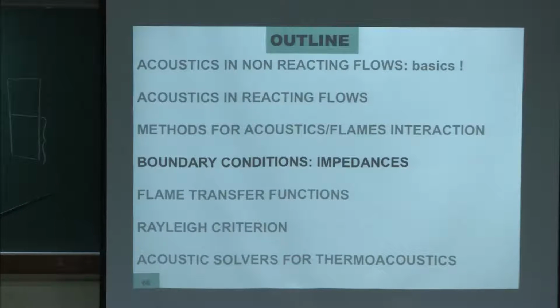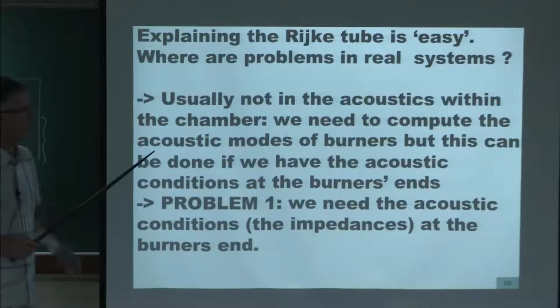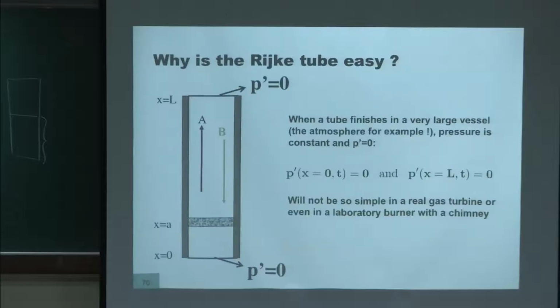Okay, I need to talk about impedances now. When I did the Rijke tube here with p prime equals 0 on both sides, that was easy, but in a real system, that's not the case. I mean, the pressure is not imposed this way. So we have to worry about the acoustic conditions in a real engine. And in a real engine, you won't have p prime equals 0. Okay, you will have something different.